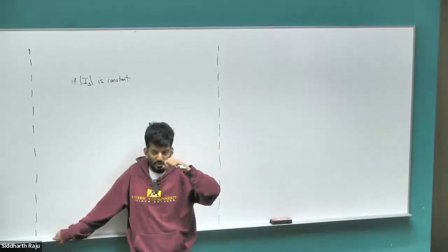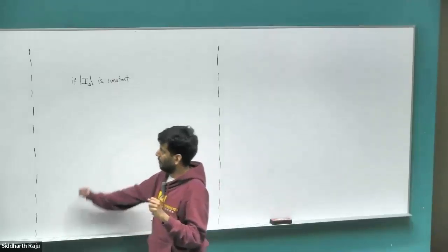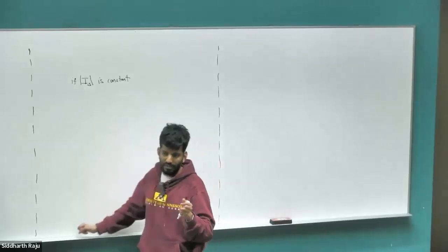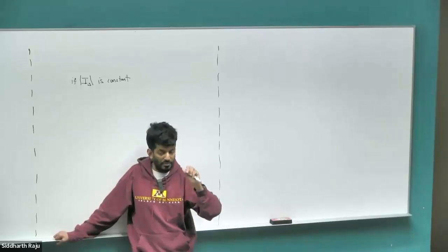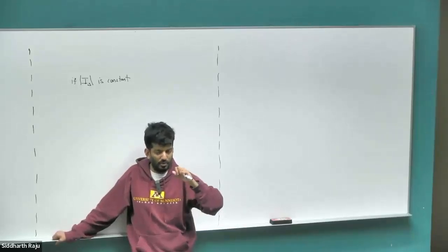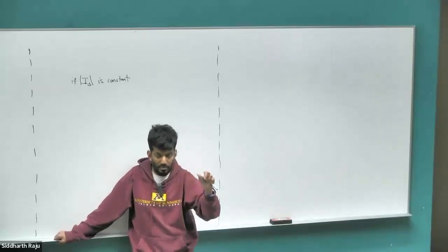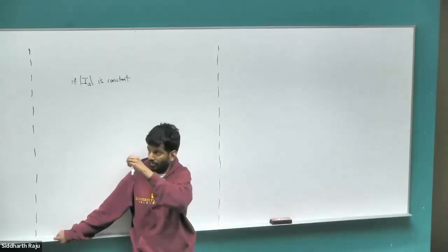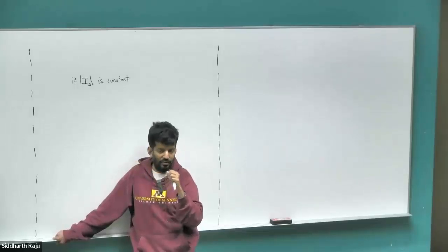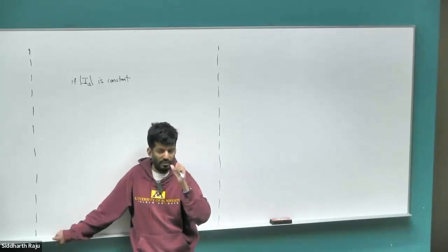And then we could design some kind of transfer function, analyze it, and design the KP, KI values, which we have done numerous times now. We can do something similar for a permanent magnet synchronous motor, but the only problem is the currents are varying sinusoidally. So how do we design a controller for it? You can keep it in the sinusoidal domain and create a controller, but it gets a little bit complicated choosing the bandwidth, because on one end you'll be limited on the bandwidth by the fundamental frequency of your electrical frequency, omega E. And when you want your motor speed to change, that omega E changes. When you design a controller, you want to choose bandwidths that are restricted in value and do not vary all over the place.